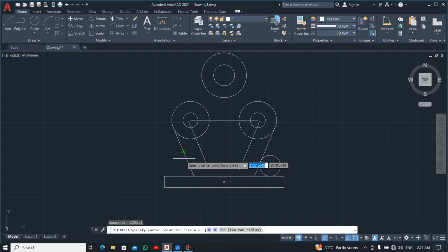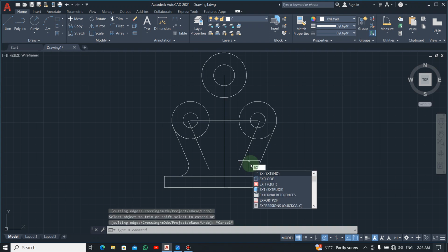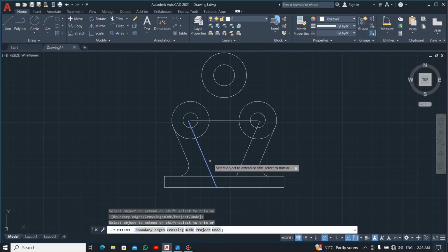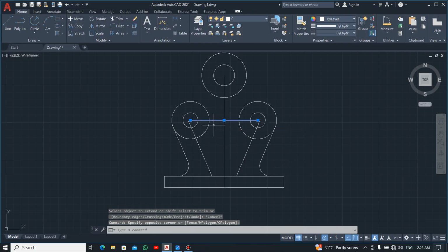The same thing. You click the circle tan radius, click this line, 14 is already there. So okay, now you can trim the unwanted parts. With that, type your shortcut TR for trim, enter. Let's trim this. We don't need this. Okay, so now let's try and extend these lines down. So EX shortcut, enter, extend. Good. All right, so now we don't need this line, can delete it.